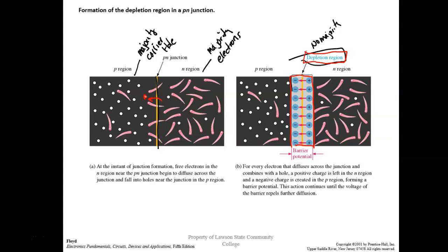So what we can do is we used to check these things with an ohm meter. Because what you would find out is that one way it would have a real high resistance, because everybody knows an ohm meter is actually a source, right? You understand that. Most of your ohm meters now are what we call constant current sources. So your ohm meter is one of these, but instead of being a voltage source, it's a constant current source.